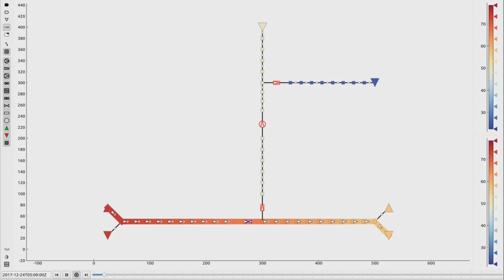Before and after each of the elements, we have a single node. The inner nodes of the network are represented by small square symbols, and for the boundary nodes where the gas leaves or enters the network, we have the triangle symbols. The two triangles pointing to the top are the entry nodes, and the triangles pointing downwards, which we are given 4 in this example, are the exit nodes. In addition to the topology, we also see the current state of the single elements in the network. We displayed the two quantities we previously talked about, the pressure and the flow.